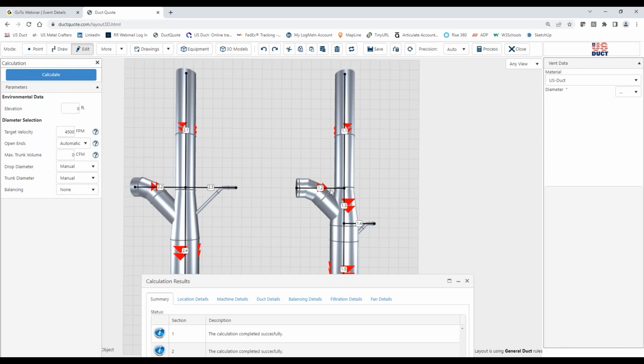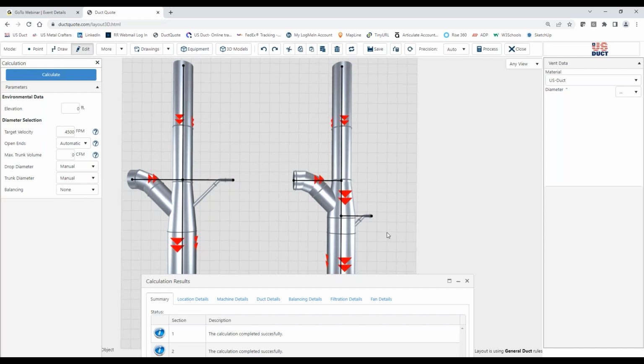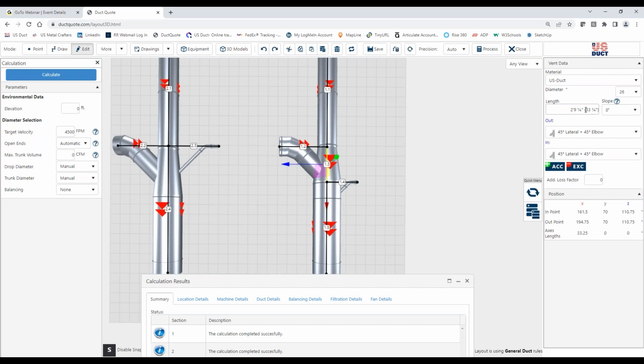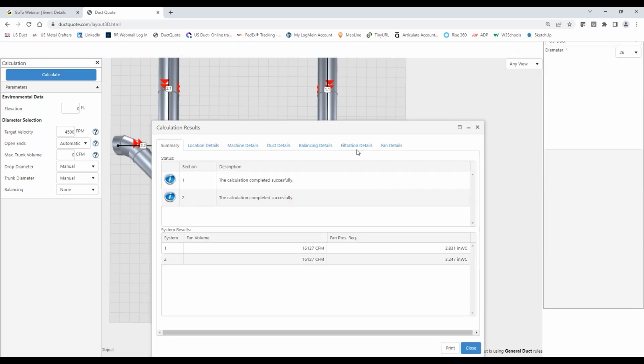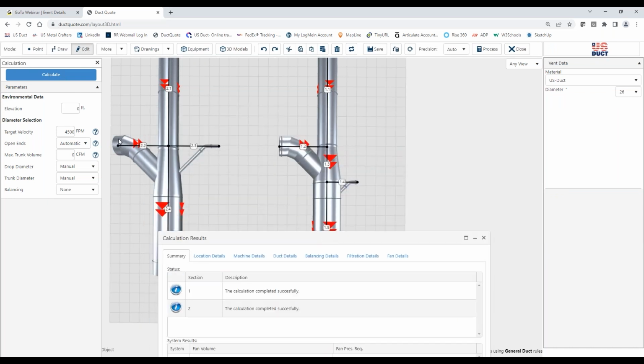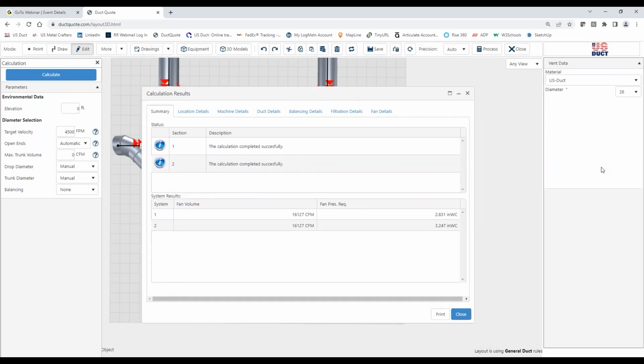Whereas here we've got the same 2 coming in, but if we move that 4-inch to its own branch, which is a little bit downstream, and it's really not that far downstream, we're talking less than 3 feet. It makes that big of a difference. So try to avoid mismatched sizes in your double branches, okay? That can save you fan pressure.